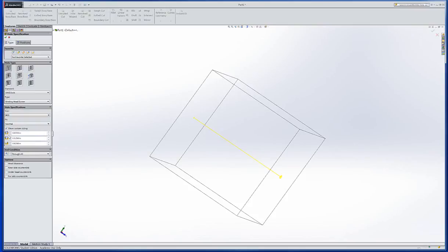Now, if we zoom in on that, you'll note that this first diameter is the 1/2 inch that we started with. So we would go to 1/2 inch on there. Somehow that got switched. The second one is the actual counterbore diameter. So let's make that 0.875. I'm just pulling numbers out of the air. And then this third one is how deep do you want that? If you hover over it, you can see that counterbore depth, and let's make that 1/4 of an inch.